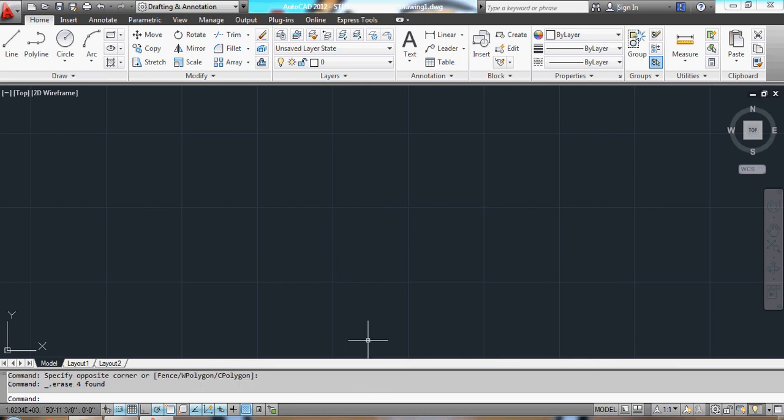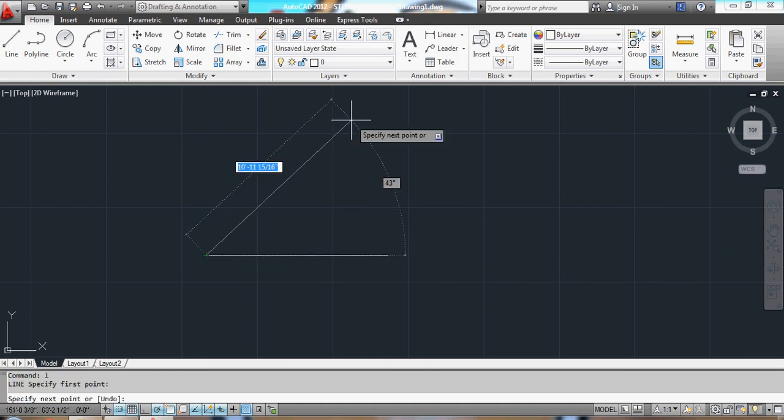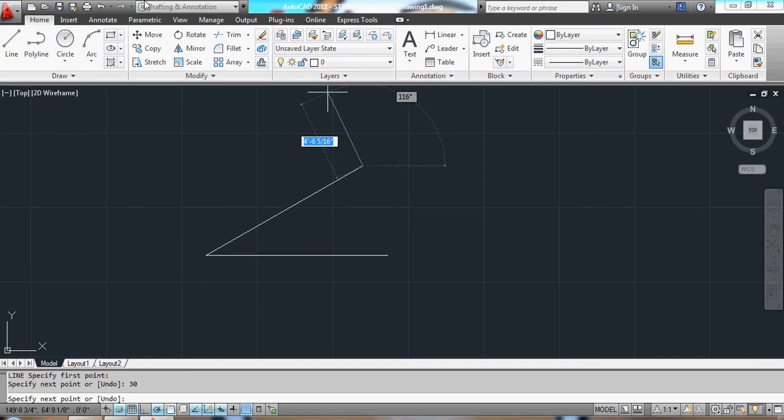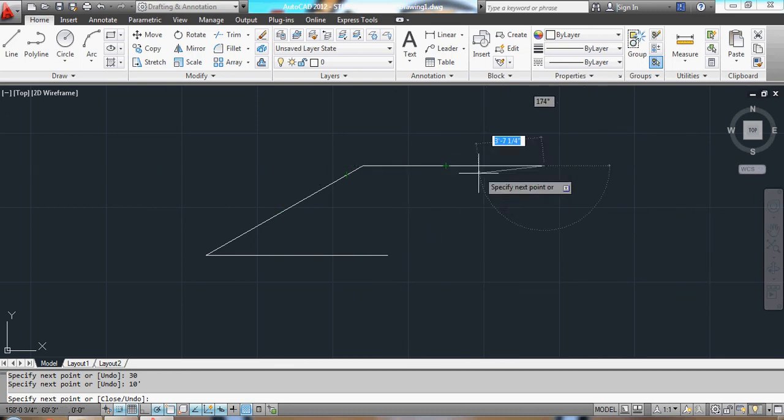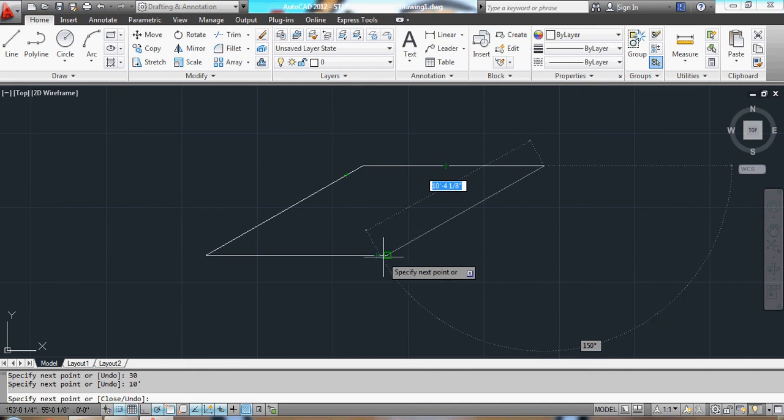It's looking good. So I'm just going to go over that one more time. L space, click, drag, we'll say 10 foot, escape, line, at the end point, click, and we'll say 10 foot, tab key, 30 degrees, enter. Actually, I'll keep drawing the line here. So I'll go 10 foot, spacebar. And now I actually don't need to make these lines parallel because I'm going to take advantage of the geometry, even though you'll see the snap comes up to make the parallel line. I'm just going to slide it down in the corner and click OK. And thanks guys, that's it.